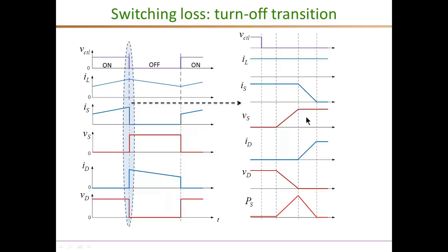In the third interval, we have the full rated voltage blocked by the switch, and the current is falling from its rated value towards 0. So once again you have high instantaneous power loss. This corresponds to the turn off switching losses. Many times the data sheets give the energy loss for a given current and voltage during a turn off, and that is this value.